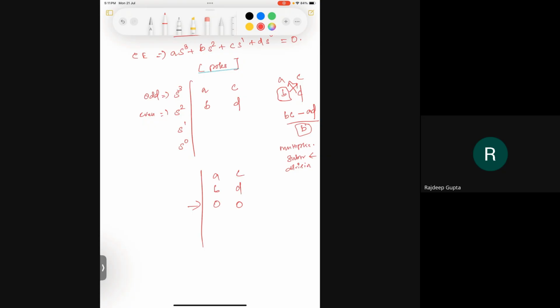So what we are going to do is replace this with the previous equation. This method has two different cases. The first case involves if only this element becomes 0 and it has some other x here. Since only the first element goes to 0, we can assume that the 0 is negligible, some other very small value, that is epsilon. Then we proceed with the same method and see whether the epsilon has changed sign in the upcoming steps. If it changed sign, we can claim that some minute amount of pole location has been shifted to RHS, so the system might be unstable.